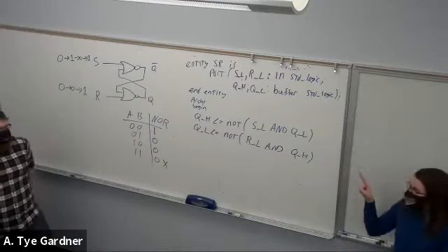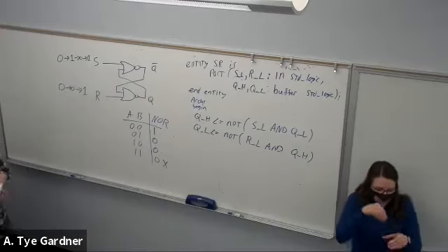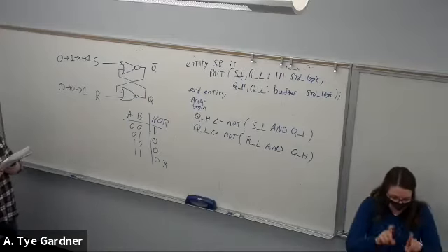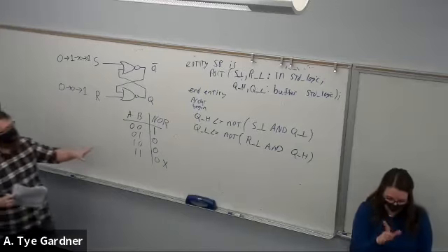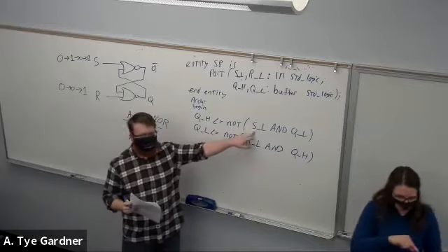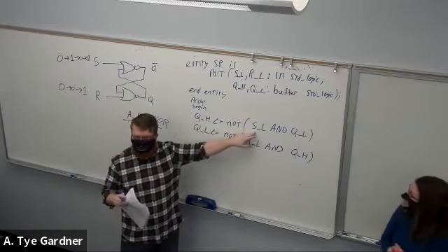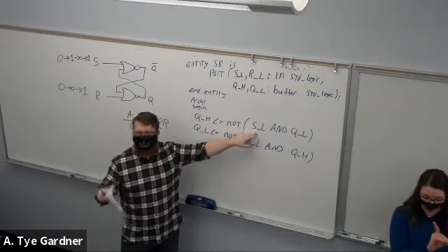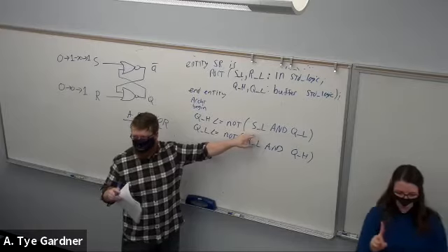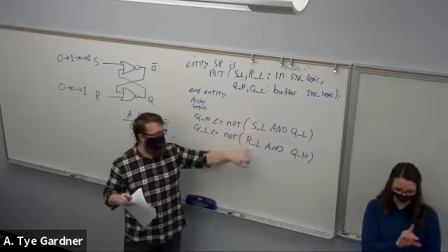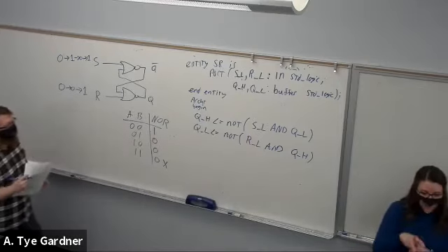Again, it can cause issues in simulation, and I just want you to remember that because I will probably ask some question around that. In this case, because they're active low, deassert would mean going from 0 to 1, so raising it, right? And we would never want to do that. We don't want to deassert the signal and assert it as a 0. Okay.